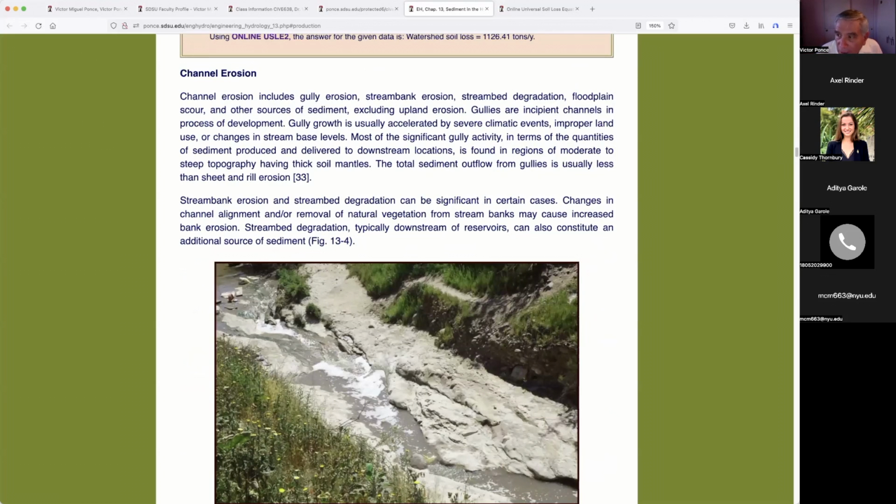Now, but that is sheet and rill erosion. What is rill? Rill is a rivulet, or a very small channel. So it's not sheet erosion, but it's rill erosion. But I submit, and I have people that recognize this, that there's really no way out there to calculate rill erosion. Sheet erosion is what Wischmeier and Smith presented us with. So everybody bundles it. It says sheet and rill erosion together, kind of, that is Wischmeier and Smith's. That's the understanding that we have currently.